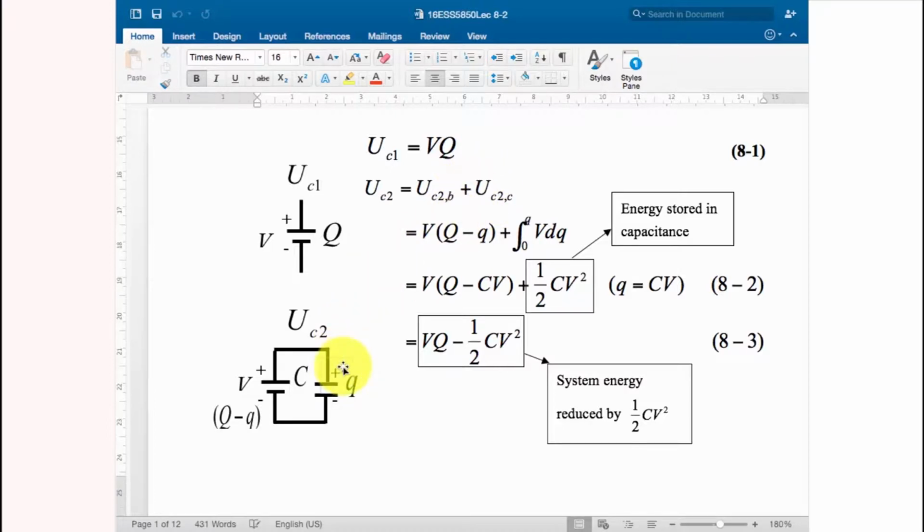But on the other hand, when we consider the energy stored inside the capacitor, we need to consider that every time you push one charge onto the capacitor, you need to resist some kind of force, right? For the first charge it is okay because there is no resistance force. But when you want to push the second charge onto the capacitor, the first charge will exert some resistance force on the second charge. So as with the third one, fourth one. So this process is a continuous process. So we need to tackle the integration. So every time you put a small amount of charge onto this capacitor, you need to integrate the total amount of energy you put in. The small amount of energy every time you push one charge onto the capacitor will be V times dq. Okay. So you need to integrate from 0 up to the small q, this total amount.